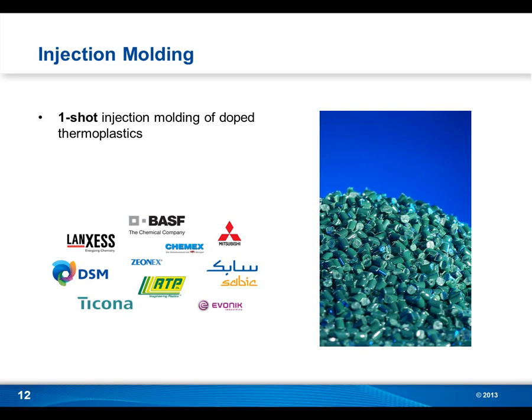In two-shot you have to freeze the design before you build your mold. So with LDS you can freeze the design way past the point of the mold. You can tweak the design after that. So your design freeze can be much later, and the ramp up to full production, to fairly high quantity production, can be fast. So short lifespan products can be run very well with the LDS process.